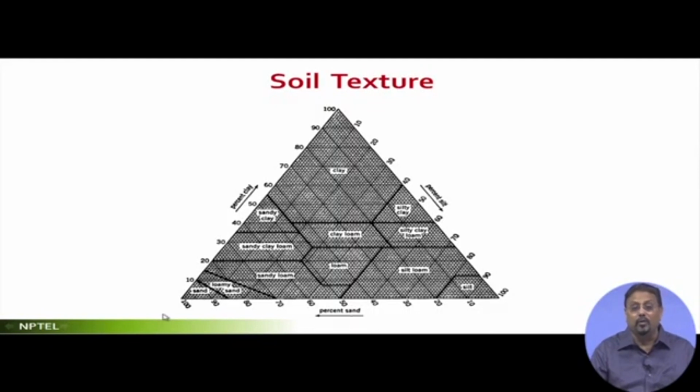Whenever we try to do some vegetation work, we try to see the loaminess of the soil. So we pick a sample of this soil from the field where I am going to work, and take it to the laboratory. There we disintegrate it and find out the different proportions of sand, silt and clay, and if we find that it is within this particular range, we say this soil is good for my vegetative purposes. That is how we work it out. Here we are saying vegetative purposes, and at the same time we are talking about its stability.